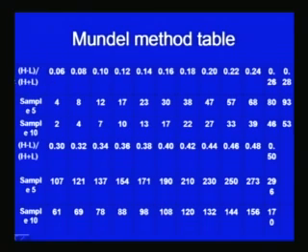This table shows the different values of the ratio H minus L divided by H plus L in these rows. Here is another set of values for this ratio, and thereafter there are 2 more rows. Here this one shows the ratio value of say 0.06. The number of observations to be taken is 4 if the sample size is 5 readings. If we take a sample size of 10 readings, then the number of observations to be carried out is only 2.